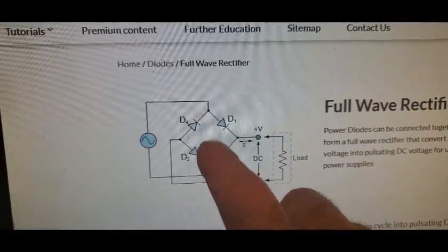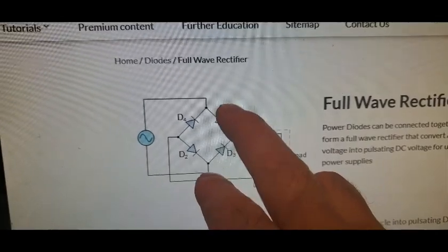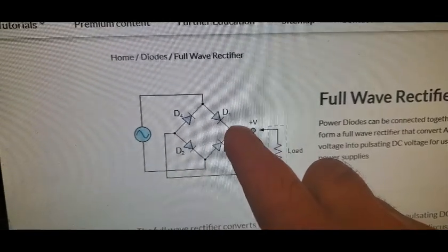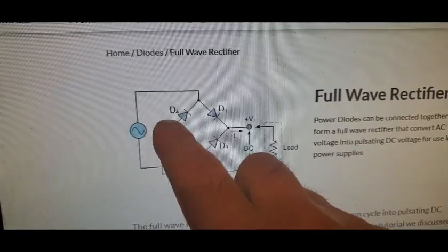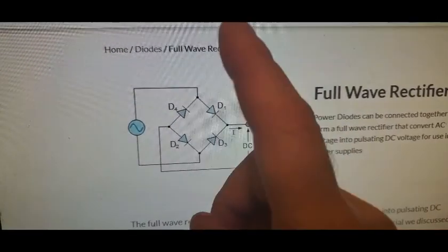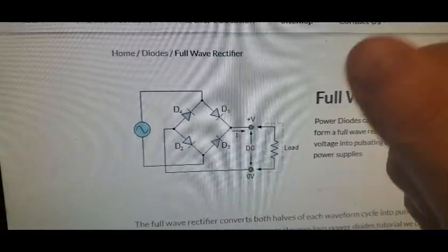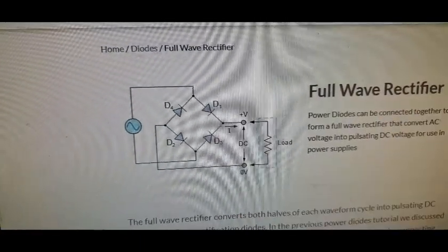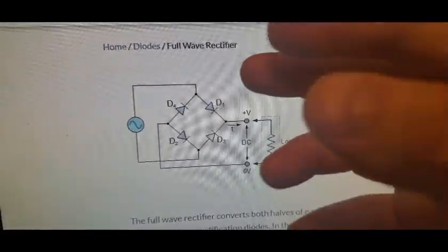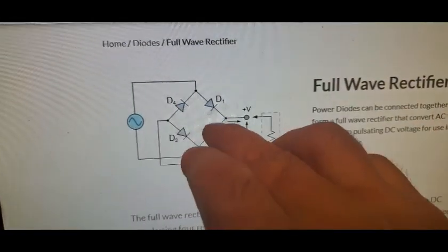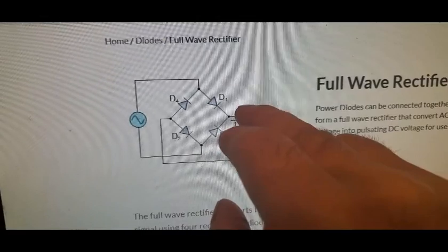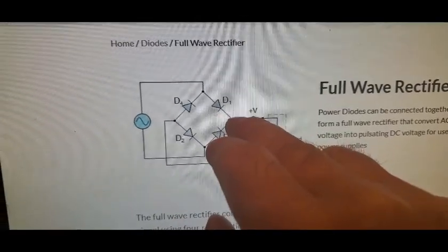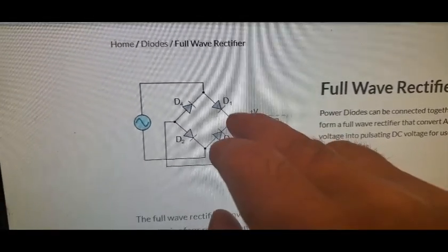But if you have a full wave bridge rectifier, this one goes through a diode, and this one goes through a diode. So now, instead of a 0.6 voltage drop, you have a 1.2 voltage drop. So again, running at 60 volts or 120 volts is sort of like, who cares? They're basically the same. Running at 4 volts, instead of losing 15%, you're losing 30% of your voltage to the coil.